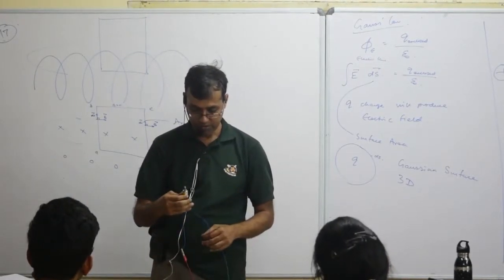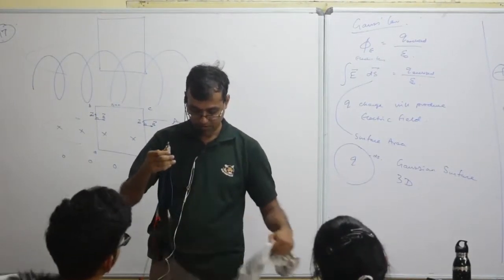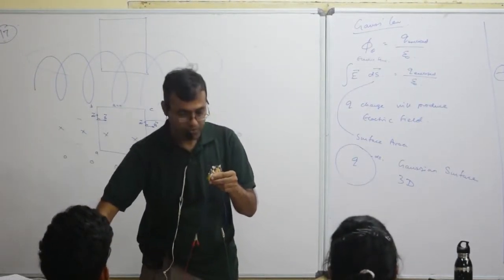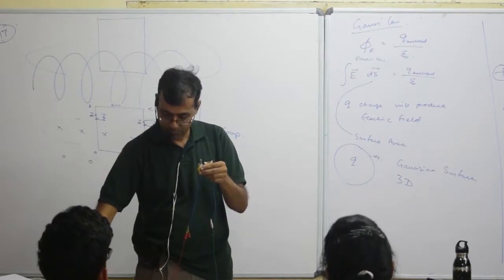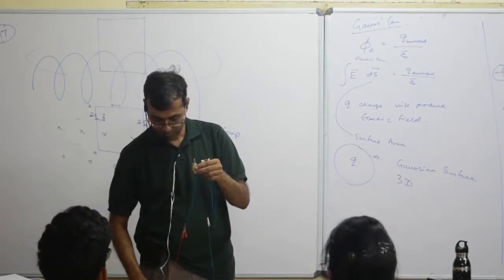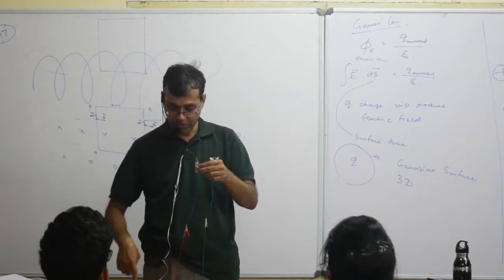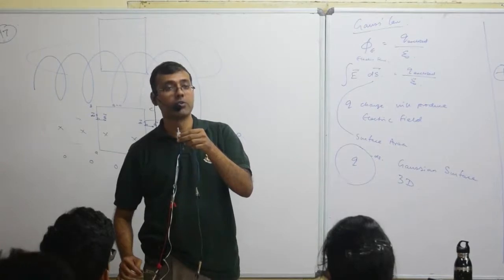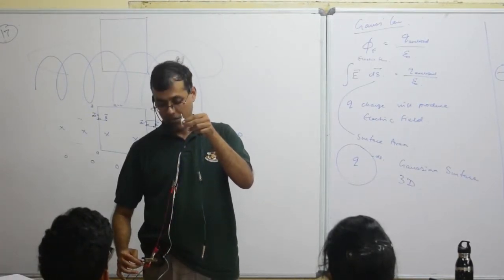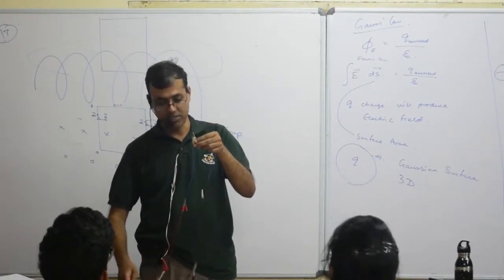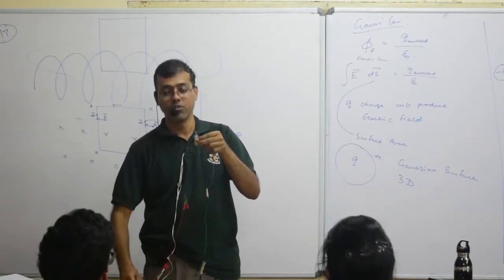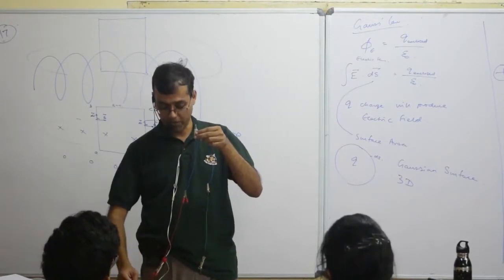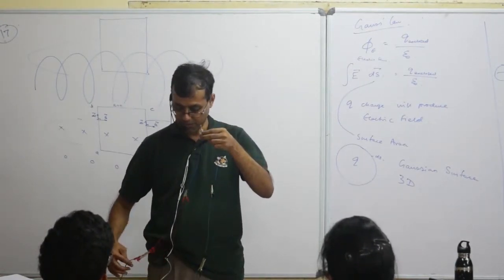Again, I have to show it so that everyone can see it properly. So if I had something like this, 6 volt. When you are doing these experiments, if this and this are touching, the experiment is not going to work. Why? It's a short circuit, right? The plus and minus, instead of going through this, will directly flow through this, which means it's not going to work as expected. So you have to make sure that these things are not touching each other.